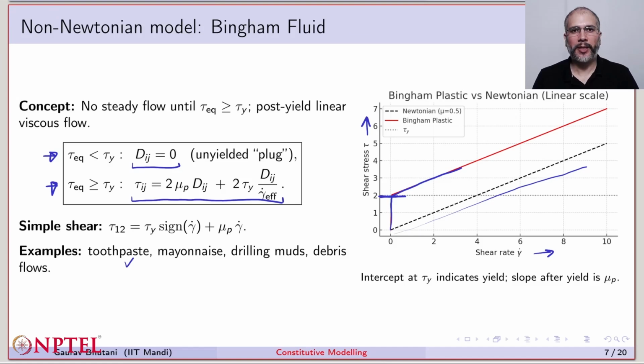When I say in the beginning nothing happens, you may see an elastic kind of behavior like a solid, where if you release the stress, this toothpaste may go back in. Other examples are mayonnaise, some drilling muds, and also debris flows in nature. Until the shear stress exceeds a threshold value, the debris stays there, and beyond that, it starts flowing like a fluid, like a very thick viscous fluid.